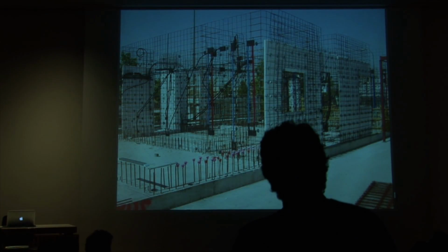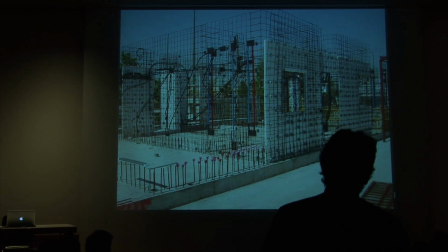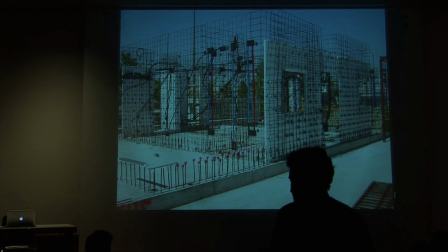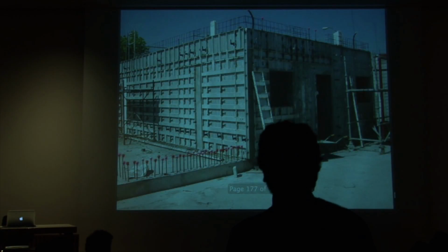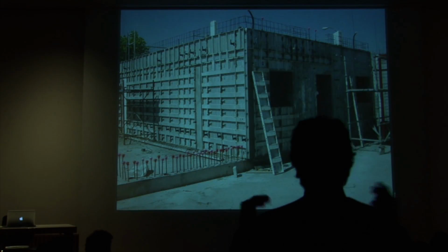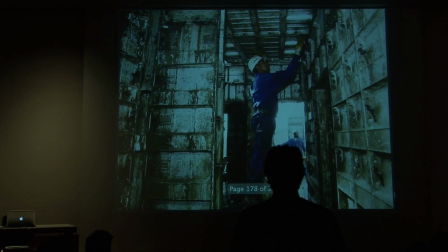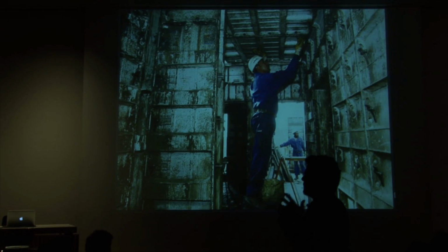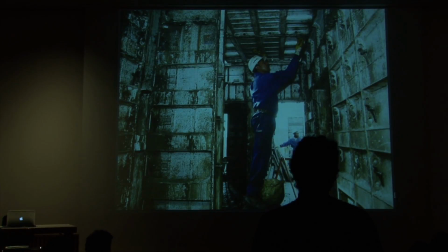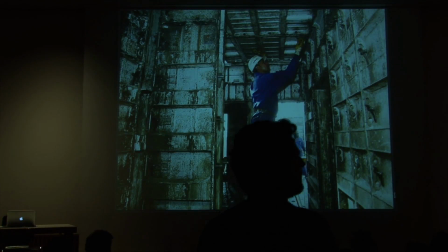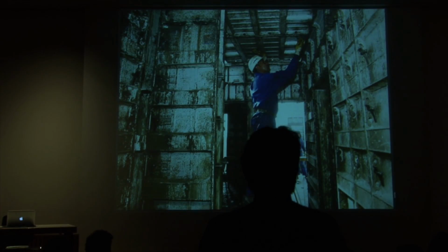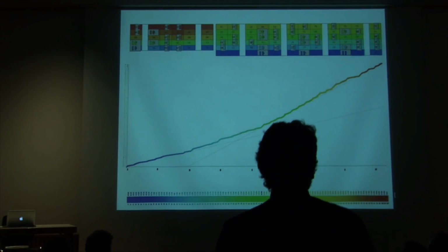First, we built the reinforcement, isolation, and services, and then we would place these aluminium casts that were built during the morning. In the afternoon, they put the concrete inside, and the next morning, they remove the casts again to put it in the next building. So it is important that they are made out of aluminium, because once it is with concrete, then you cannot use the crane because the pieces are inside, so they are removed by hand. And that was done 1 per day.